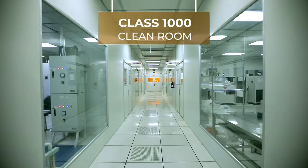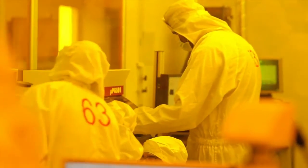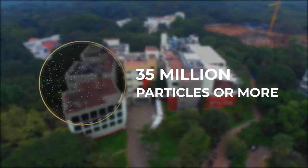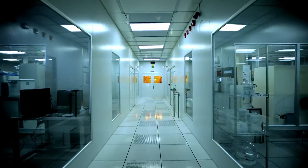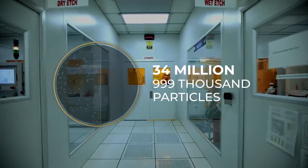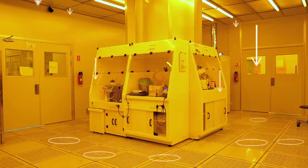This is a class 1000 clean room, meaning that the number of dust particles greater than 0.5 microns in size in 1 cubic meter is less than 1000. Outside the room, there are 35 million particles or more in the same volume. Yes, we breathe all that. The air that enters the room is put through filters to remove 34,999,000 particles to make it clean and exits through these holes in the floor.